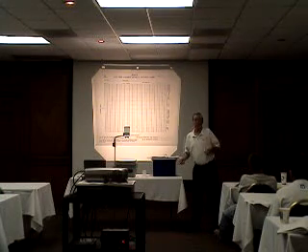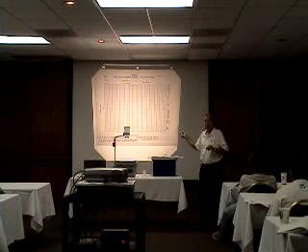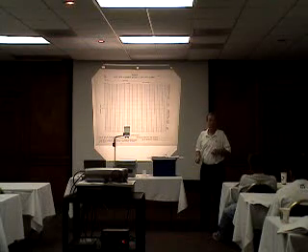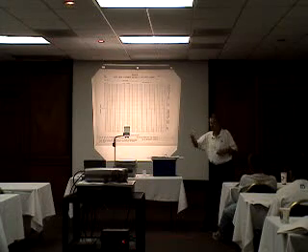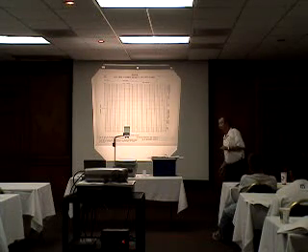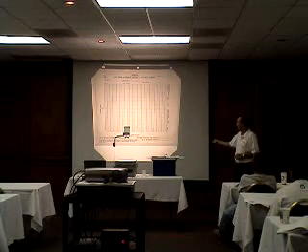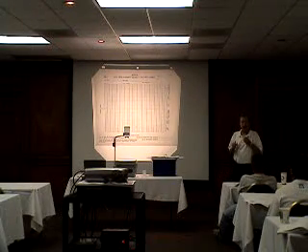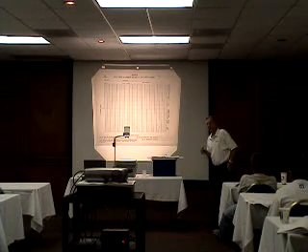If you're plotting binder and say your target on your formula was 5%, that line represents 5%. If you're plotting the .075 sieve and that's 4.2, that represents 4.2. Whatever your target is for what you're plotting, that's the line there. He plots his individual test results, and like I say, if you count across there, you'll see you can get 25 test results on it. He plots his individual test results, as well as a moving average of the last 4 tests.